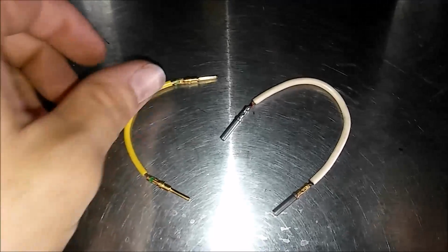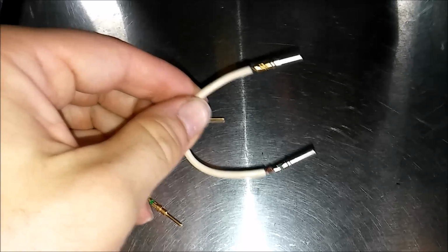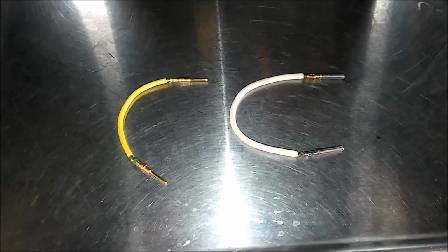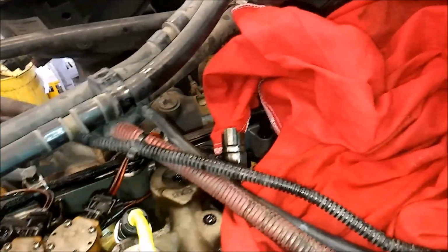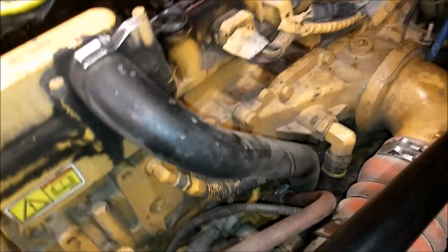Now, you don't really need much specialty tooling to troubleshoot CAT sensors because the ECM does most of the troubleshooting for you. What you do need is some little Deutsch connectors, or you can use a paper clip, or you can make these up. These work really well, and I'm going to show you why. So we're going to unplug that new sensor we installed there because we need to troubleshoot this circuit first. And as you can see, it's a 3-wire circuit. The triangular ones are 3 wires. If it's flat, it could be a 3 or a 2-wire. And CAT's pretty universal. They use Deutsch or AMP Seal, but they all use the same pins and sockets.